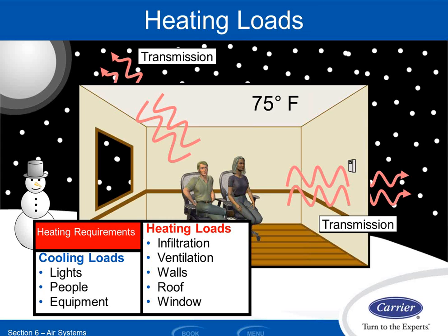So if it's 10 degrees outside versus 74 degrees outside, it's going to move heat out of my building much, much faster. So I still have the transmission losses. I have infiltration, right? Any of that 0 or 10 degree air leaking in during the wintertime is going to be a penalty to me, and I'm going to have to heat that up. But there is one thing you'll notice that is missing from this discussion, and that is the solar, right? You would think logically that the solar gain would be a benefit to me in the wintertime. I would get that free heat.